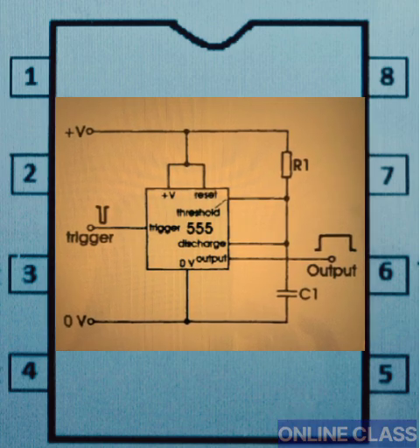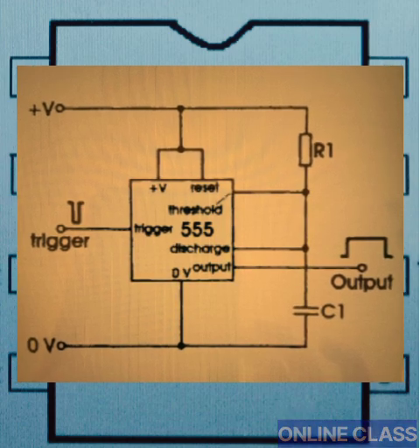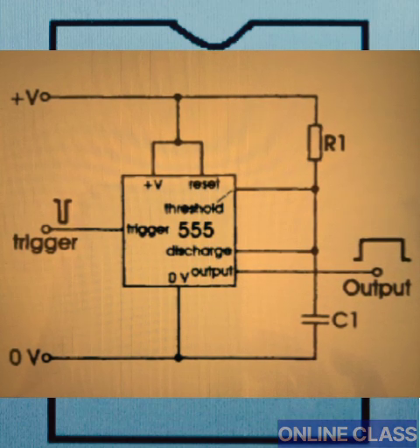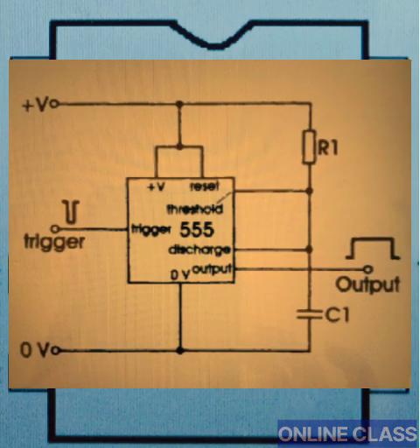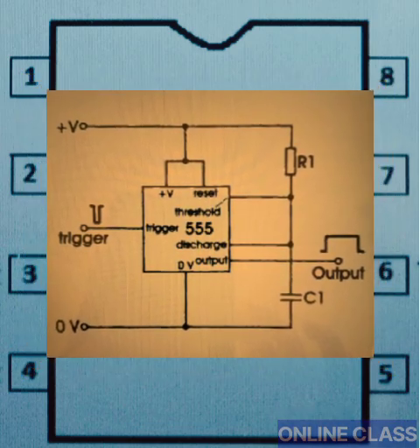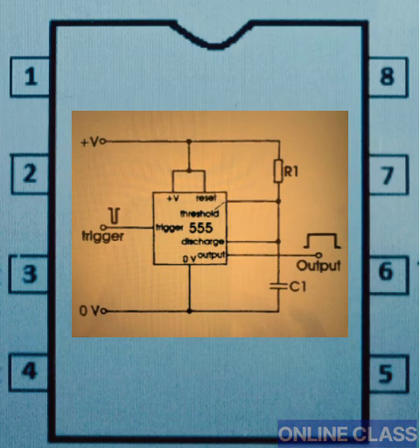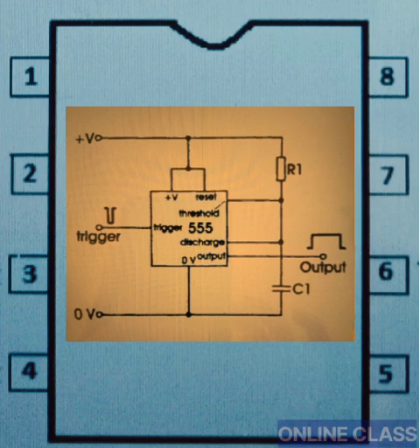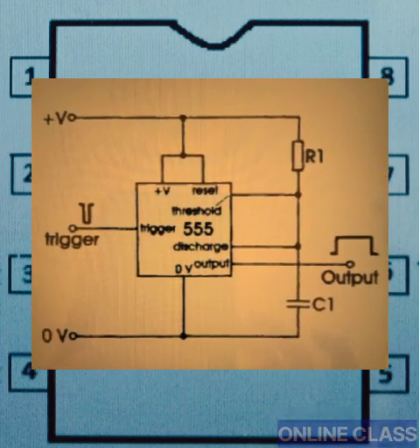As shown in the image, this circuit only requires 3 components compared to the 7 components needed for a BJT monostable, making it much easier to assemble. Additionally, due to its design, it offers more accurate timing intervals than the BJT monostable and can generate output pulses ranging from just a few microseconds to several hours. The timing is determined by the charging of a capacitor through a resistor, with the pulse duration set by selecting appropriate values for R1 and C1.